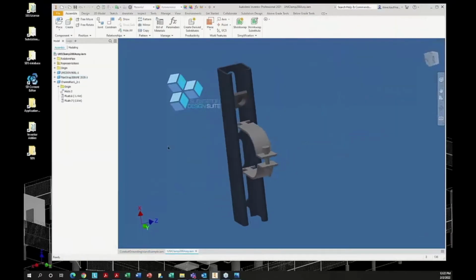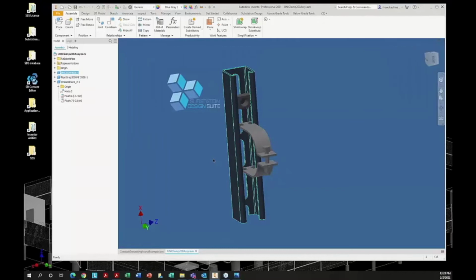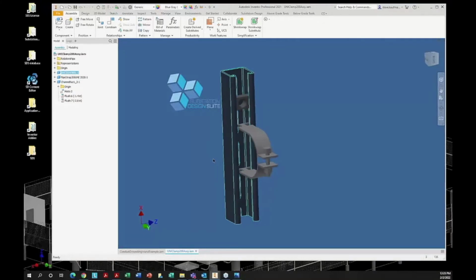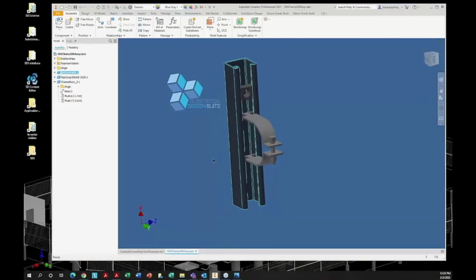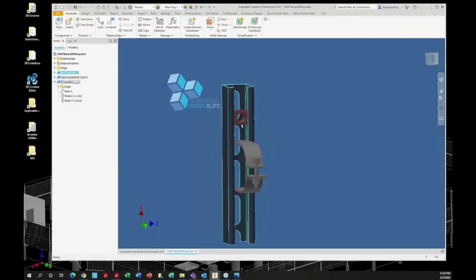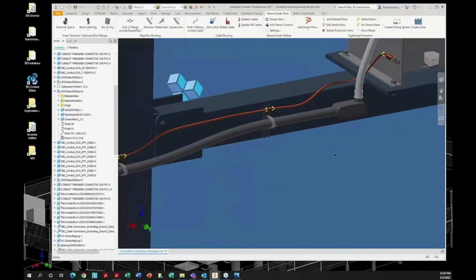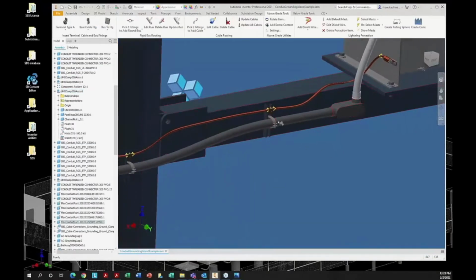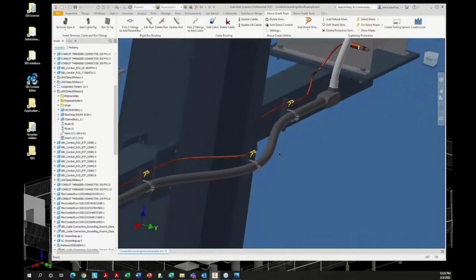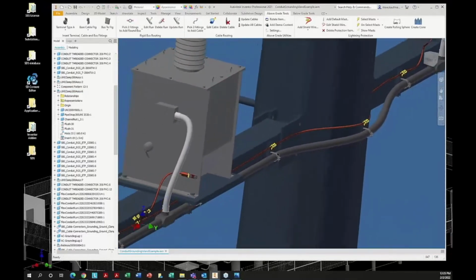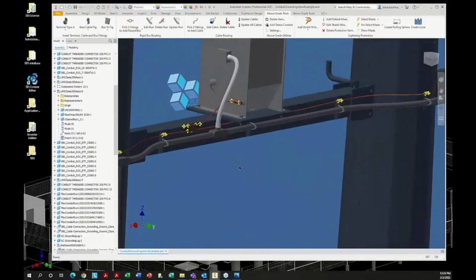You can see I have my pieces here, utility content, utility content. This here, Unistrut, is in our training catalog, our training models that you can grab as well. This guy's in utility content as well. So we have these pieces here. So now it's just easy. I place this in line with this hole, work it out, and then away I go. And you can see it's coming across, coming down, and I'm running that.